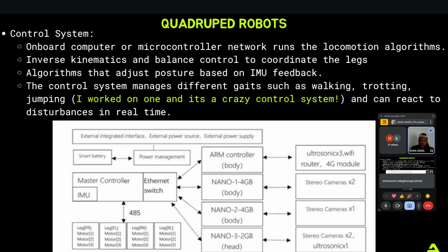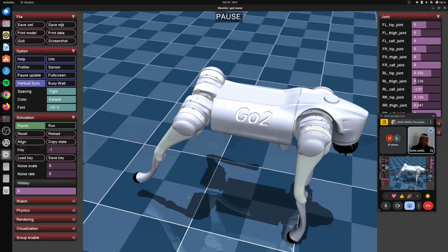Another thing I would also want us to look at is something called 485. 485 is a connection protocol. For those that are conversant with embedded, we have UART, I2C, and then there are a lot of connection protocols with their advantages and disadvantages. But there's a reason why I am pointing out 485. It's one of the nice ways I've seen for communicating in a robot.